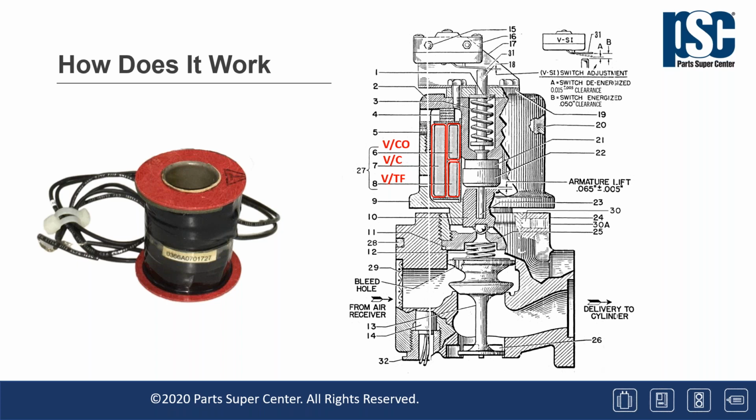By allowing current to flow through the VC winding, which is item 7 in the line drawing, the pole piece, item 22, becomes magnetized and generates a flux in that 65 thousandths air gap between the magnetized pole piece and the top of the pilot armature directly below it. The resultant magnetic field will lift that pilot armature and close up that 65 thousandths of an inch gap, overcoming the pilot armature spring bias above. So the next slide will show graphically how that pilot armature looks in the raised position.